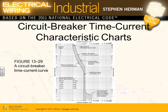You will be dealing 90% of the time with air. The air ones are called molded case circuit breakers, insulated case circuit breakers, as well as power circuit breakers and medium voltage circuit breakers. The oil ones have a different type of design. The vacuum ones are typically for medium voltage and so forth.